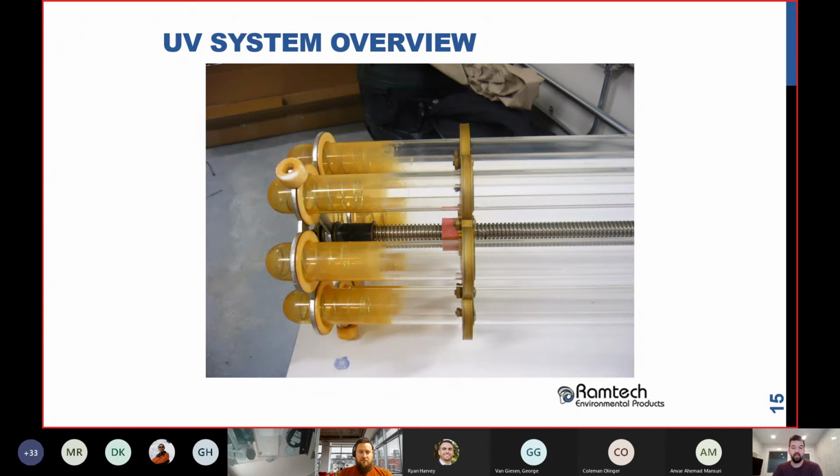This is just one of my favorite photos, to show what low UVT can do to a UV system. This is actually a drinking water system, but it's the same principle. On the right, you have sleeves that have been cleaned by this wiper. It's just a mechanical screw-driven EPDM or Viton sleeve, or ring, right on the sleeve.